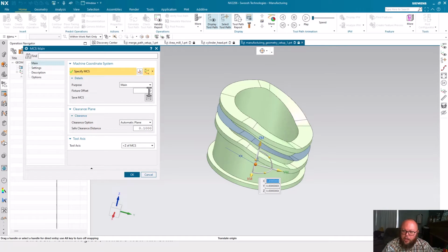Say I don't have any coordinate systems set on my machine tool. I know, for instance, on a particular machine, my XYZ0 is right at the center of the table and the face of the table. So I can mount a part on a vise, in a chuck, or whatever the situation might be, and as long as I'm reasonably close, I could go ahead and do some probing operations, for example, and probe my XY center, Z0 face, and use that to set my work offset.